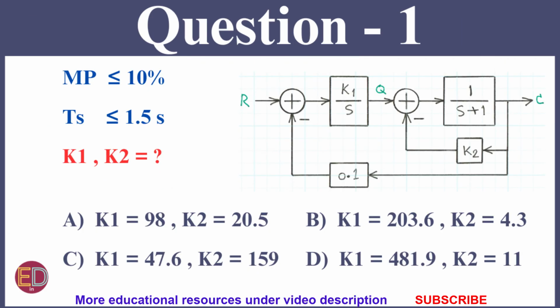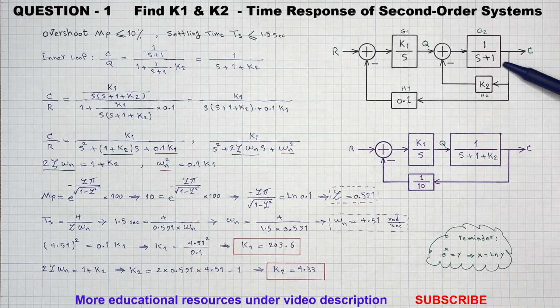Question 1. For this feedback control system, we require a 10% maximum overshoot and a settling time of 1.5 seconds or less. We are asked to find constants K1 and K2 to meet the requirements. To solve this problem, we start by simplifying the inner loop containing G2 and H2 and determine the transfer function relating C and Q. This results in the equivalent block diagram shown here.